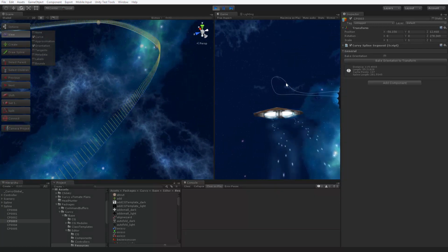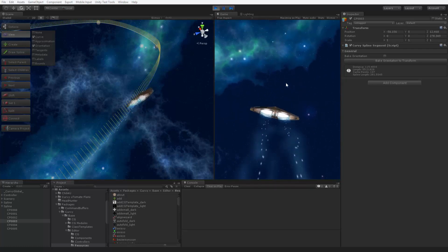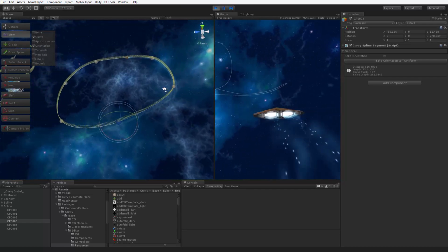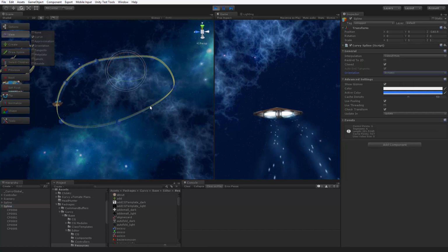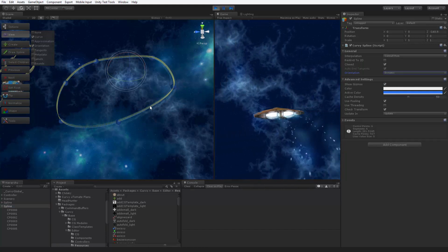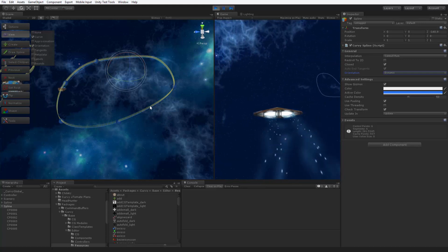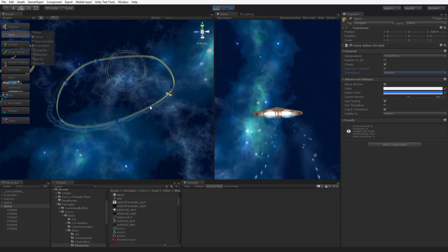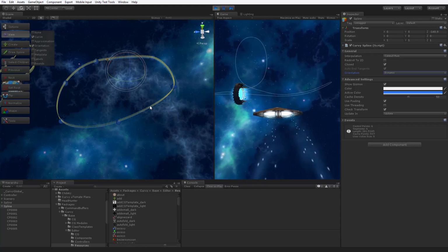But having every single control point exert influence on orientation can be inconvenient. There is a third orientation mode, dynamic, which solves that. In it, orientation is not hard linked to every single control point. Instead, it is controlled by specifically marked control points you can choose, which are called orientation anchors, and is smoothly interpolated between them using a rotation with the least possible angle.